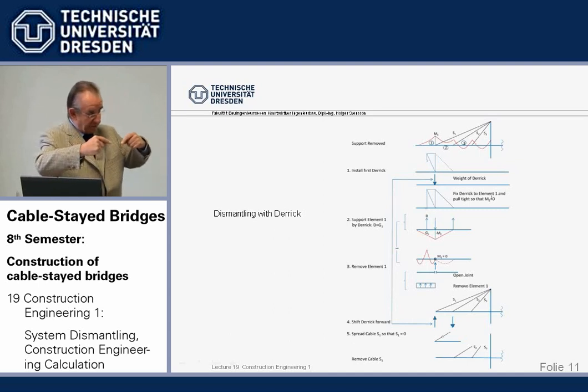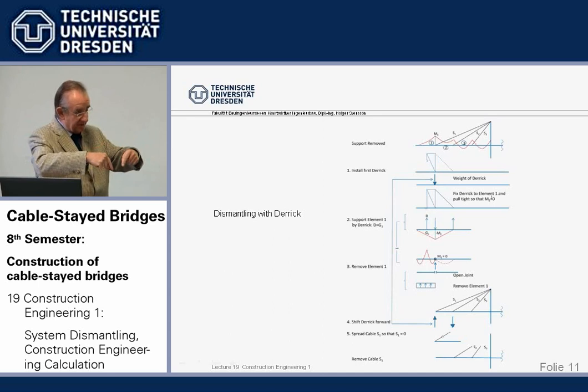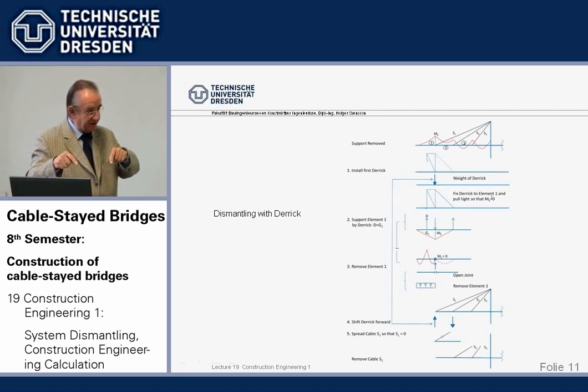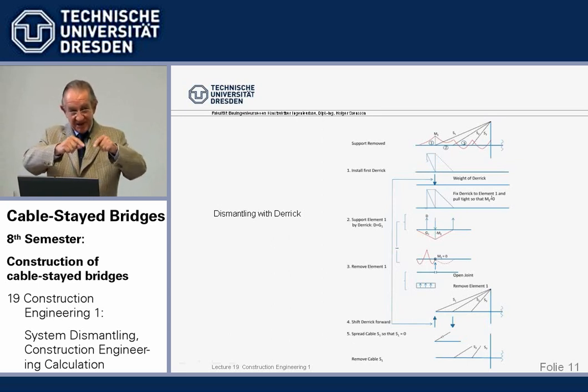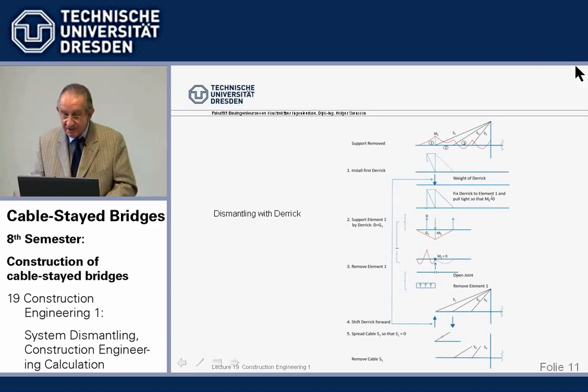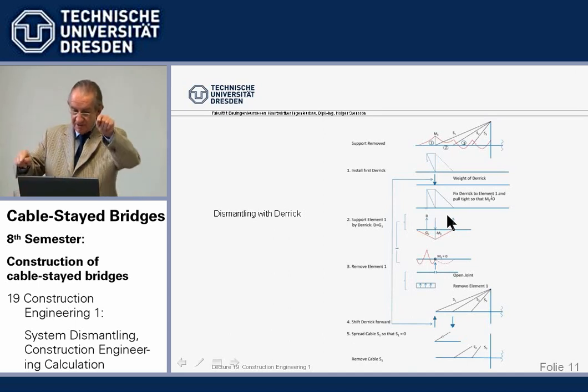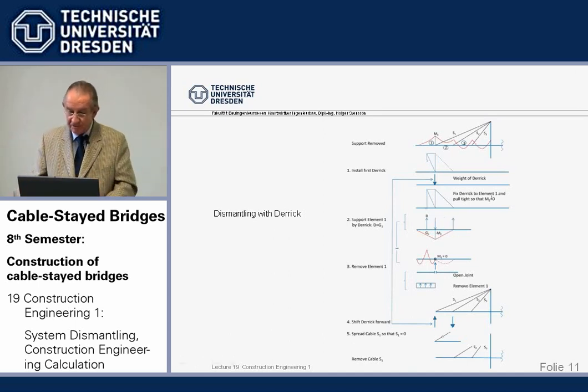Again, when we have a floating crane, we have the same derrick reactions, but, so to say, on the water. The beam doesn't feel it. That makes life so much easier there. But if we have true life and we have a derrick, then the weight hangs in the derrick and the beam still feels the reactions, which I have indicated here with this couple, which tries to overturn.